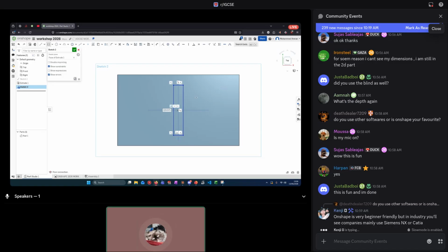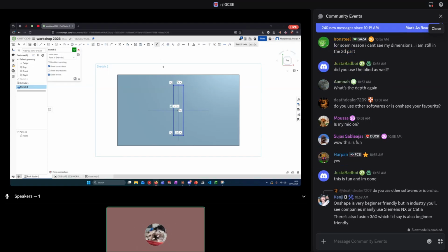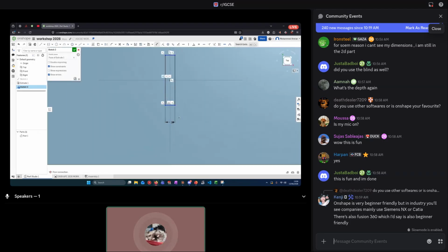After I drew the rectangle, I'm going to want to start to dimension it. So I go to the dimension tool, press the dimension tool, make sure it's selected. Okay, click on the side, come here, and then click 10. Type in 10. So now it's 10 mm thick.